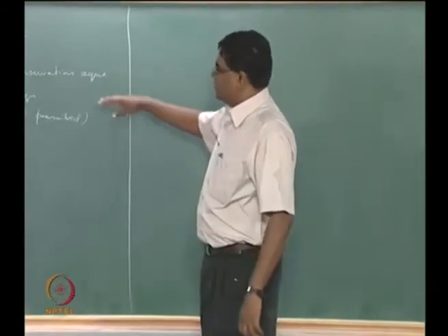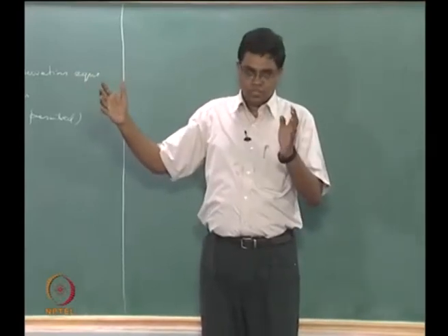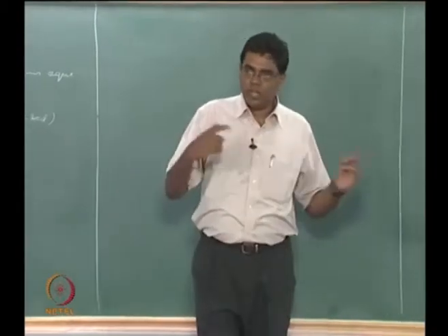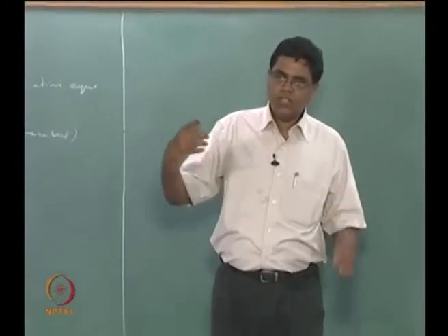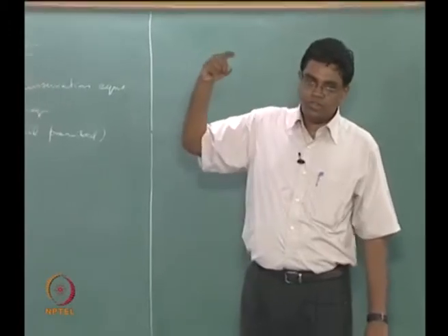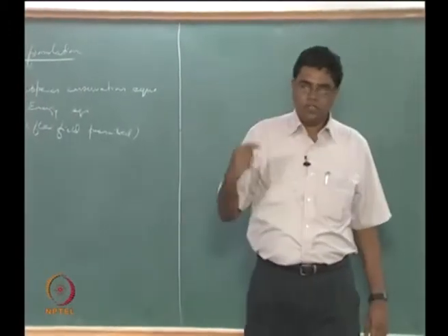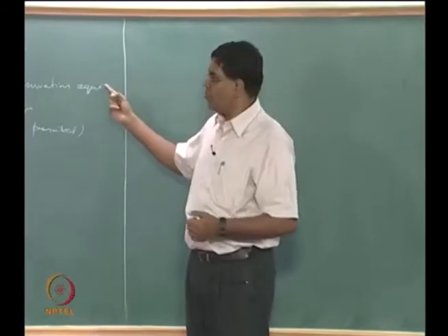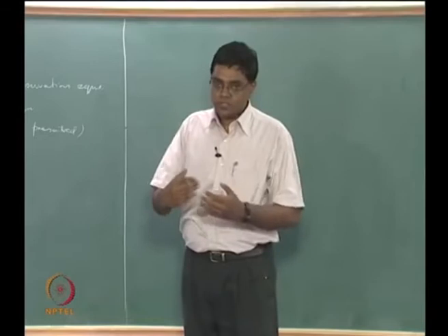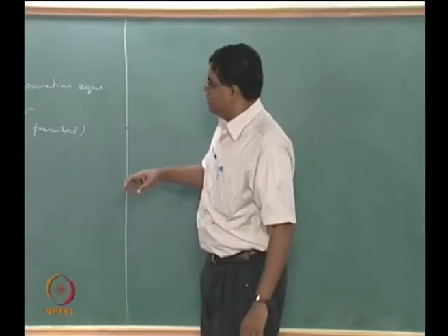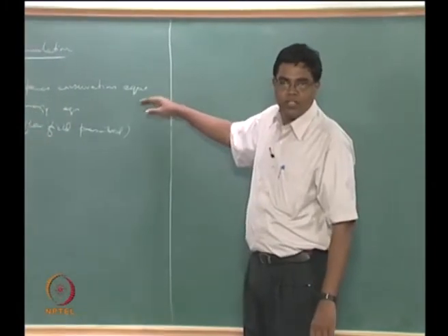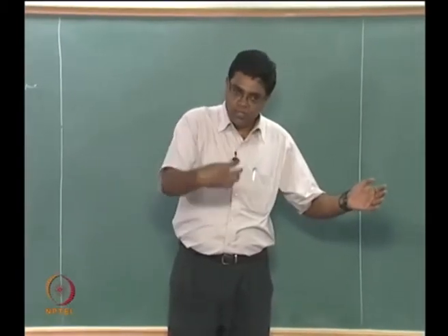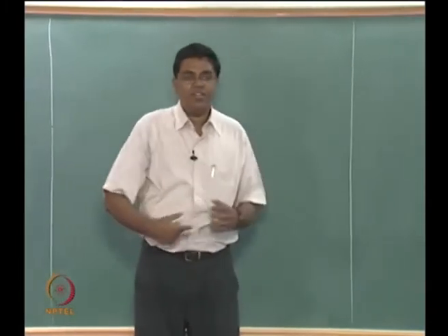Well, if you think about it, the species conservation equations contain the capital V, the diffusion velocity, okay, the species diffusion velocities, which are in turn given by the multi-component diffusion equation. So you now have these n equations relating to 3n equations for the 3 components of this multi-component diffusion vector equation, okay, and those are in xi's, whereas this is in yi's. You now have to have an additional set of n equations to relate xi's and yi's, so that's complicated enough, alright. And then you have this energy equation which has lots of terms on the right hand side, and each of those terms has lots of terms in turn and so on, so it's actually a very long equation.